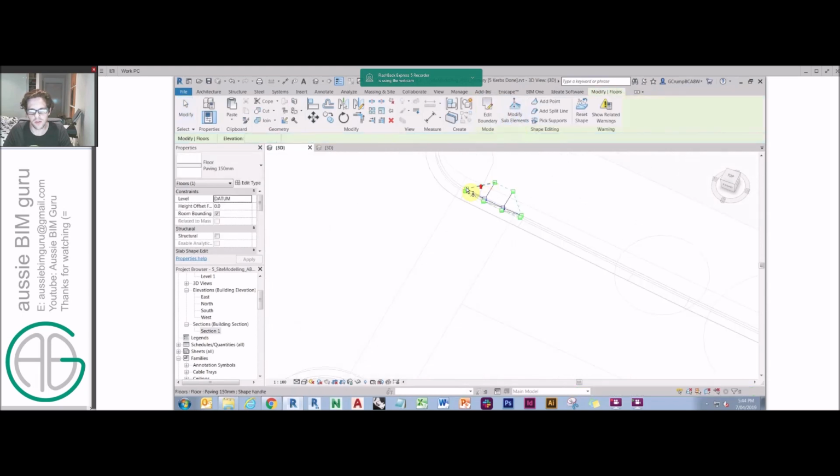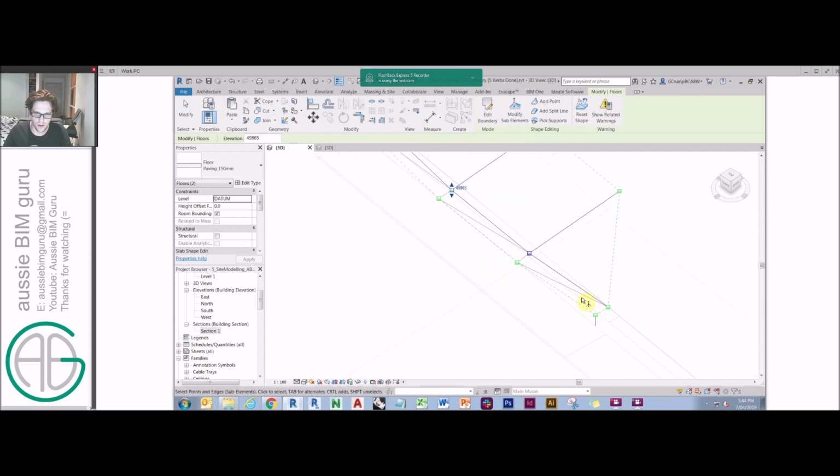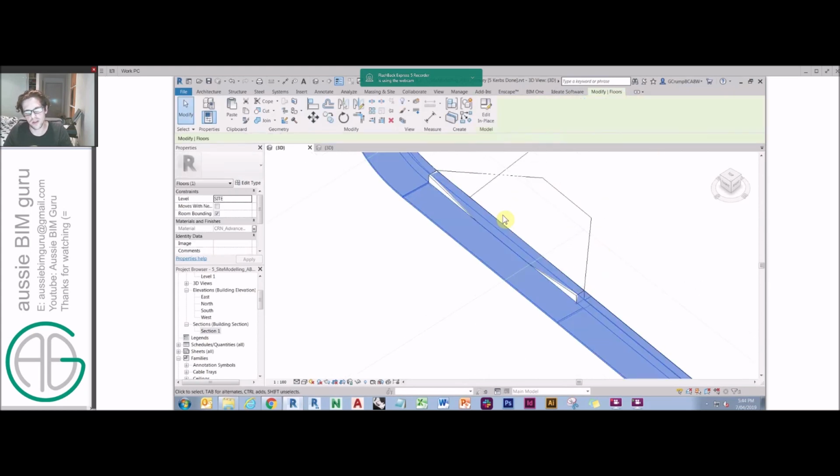From there, I've modified their subpoints, and that's basically just to match the height of the curb to the height of the topography. I had to do a bit of finessing to find the right height, and then I've lowered these down to meet the curb so that we're going to fold our curb downwards. The only issue after this is obviously the curb overlaps the curb ramp.